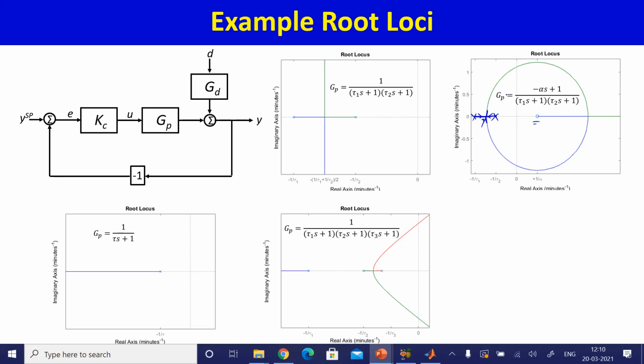So one of the branches, and in this it is shown as the lower branch, ends up at the 0, the other branch ends up on the 0 degree asymptote, and so that's your root locus. So when you apply the angle condition, if everything is in the left half plane, you use the rules that I discussed in the previous lecture.